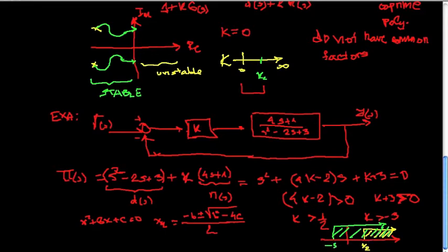So finally we obtain that the domain of k, the stabilizing k, is going to be from 1 by half to plus infinity. Okay? This is our solution. Those are the stabilizing gains here, that completely ensure the stability of this system.